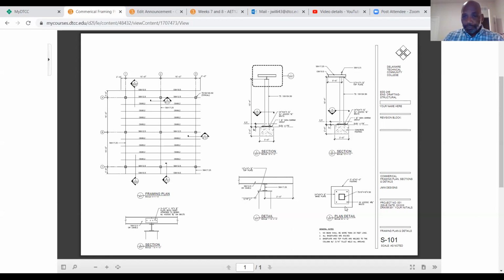Okay, good. Now, back to the plan detail. We don't have any dimensions, but you're going to put all this annotation here on 004. Okay, 004. All right, and then that leaves the general notes, which you're going to actually draw on paper space. Okay, and we can just put those on the S anno note layer, S anno note for the general notes.